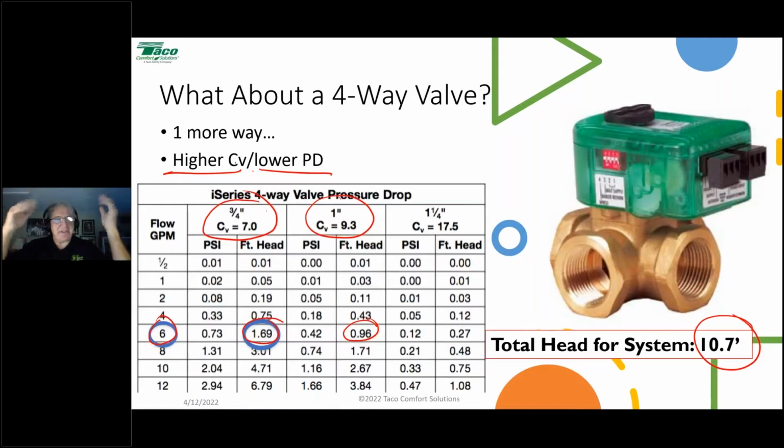Let's say there's no call for heat, and then all of a sudden, okay, we get a call for heat. The valve says, based on the outdoor temperature, I need 120-degree water going through the radiant system. Okay, that's what the outdoor sensor says. The sensor on the radiant supply pipe says, hey, the water temperature is 90 degrees. Okay, my pumps are running.